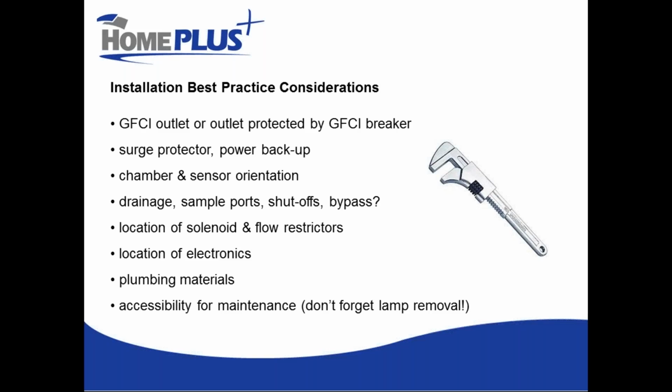On the top, it'll tend to pick up air bubbles that will interfere with the sensor reading, and on the bottom, it can be an area where sediments and debris tend to settle. So in most cases, chambers should be vertical. Pay attention to the manufacturer's guidelines there.